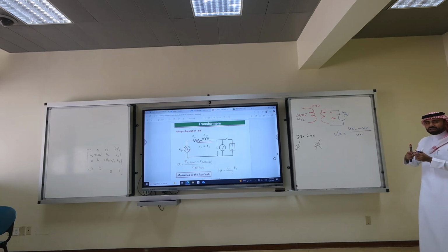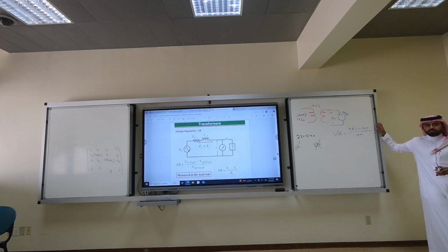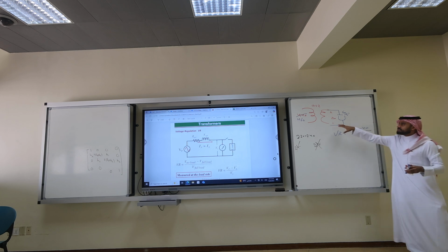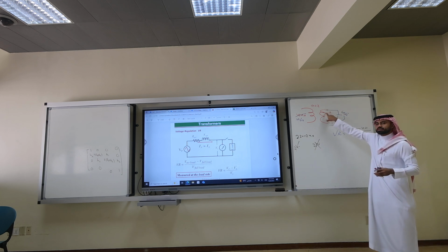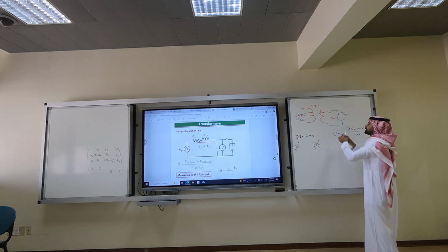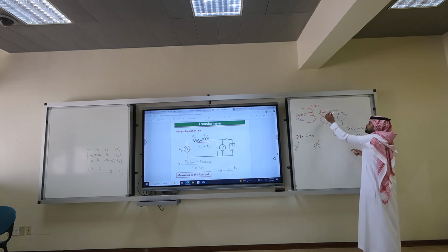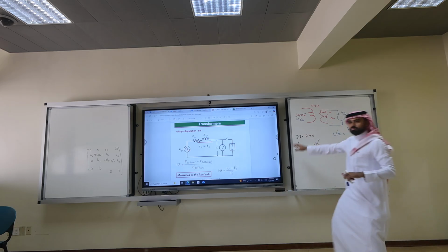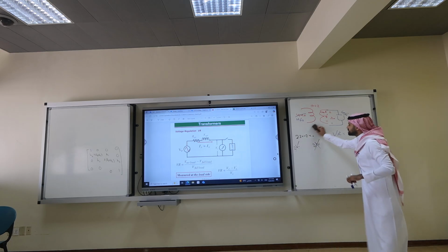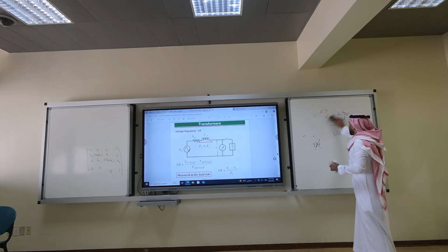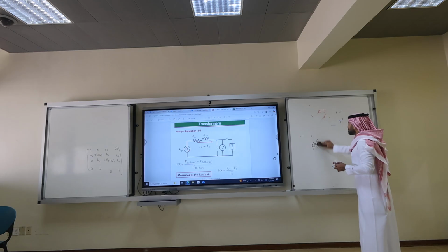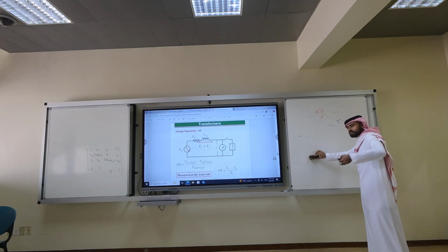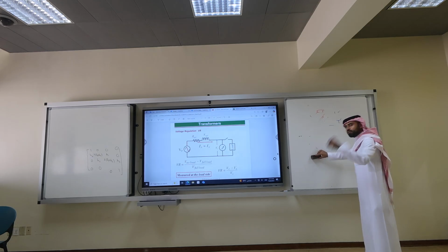Something like that. It may not be clear, but we'll solve an example. It's not 440 when you connect the load, it is the voltage that appears here after the reflection. Completely practical. This is not accurate. We need the exact numbers, but this is just an estimate. Why is voltage at no load higher? Because Saudi Electricity Company fixed the voltage at this transformer at 460.